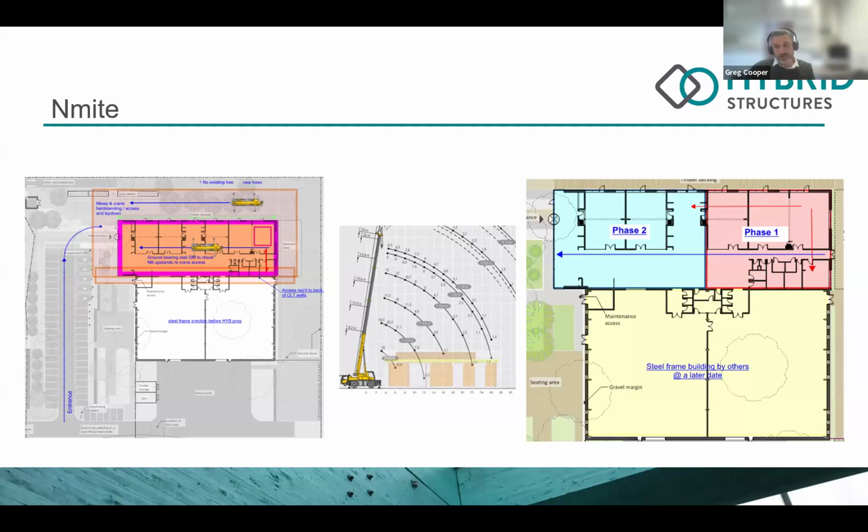The structure as it was built is actually quite a unique structure. It works like a house where everything wants to thrust out. So until everything's tied and put together, we had to build a ring beam with the glulam and then lay the CLT on top with a significant amount of temporary works to prevent it from spreading. Ultimately, that all worked. We couldn't get the crane to work here, it was over there. But ultimately, with a 50-ton crane, we were able to erect the whole structure.